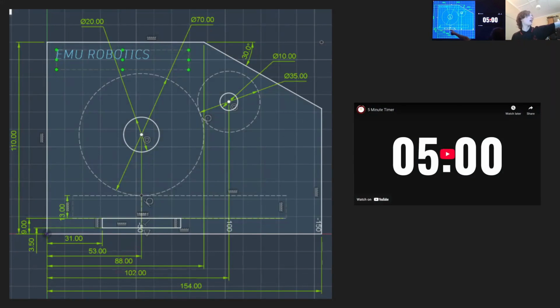The other thing I need to highlight before I get into showing you how to make this is this dimension here. Some students couldn't see that there's actually a center line along this. The reason why you don't need the dimension for the width of this is because of that being symmetrical. I think that should be all of the info you need.